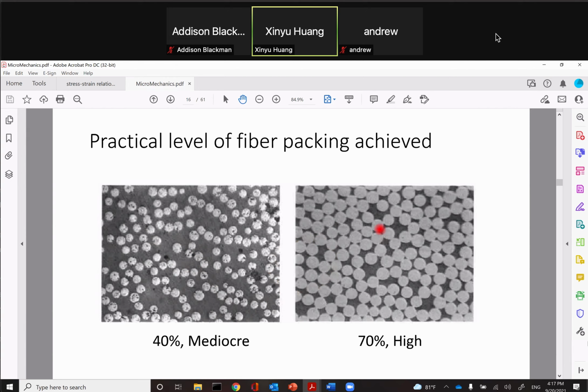This is much less. See, the fibers are much closer. Again, there are some resin-rich regions, but much less than this. Okay. This is one important parameter. This will change your material layer properties greatly. Your Young's modulus in the fiber direction in this one will be much less than this one. This is much better. You got a stronger material, right? That makes a lot of sense.